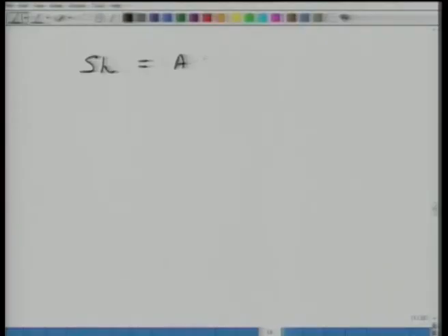Okay, so what we do now, we take up 3 well-known theories. We are writing here that the Sherwood number in general can be written as a function of Reynolds number and Schmidt number. Of course, there could be more complexities here, but the question is that in all these cases, A and B, these numbers have to be determined experimentally. There has to be some experiment behind this to calculate these different coefficients here.